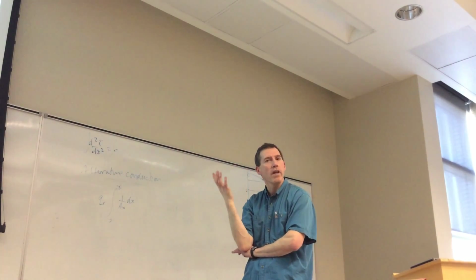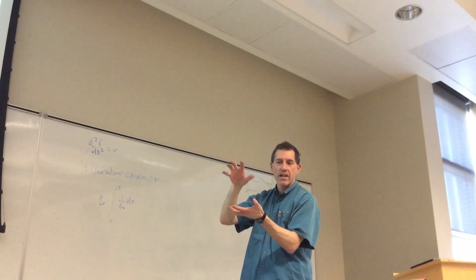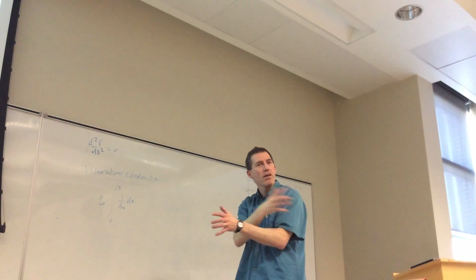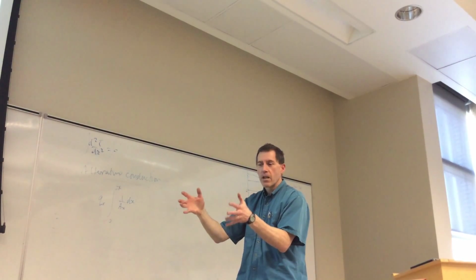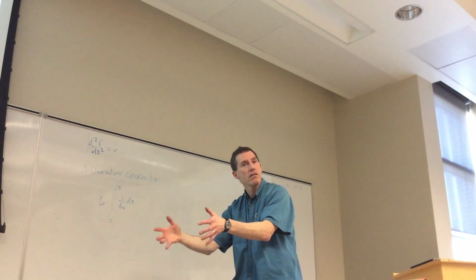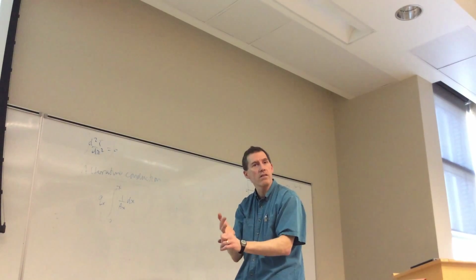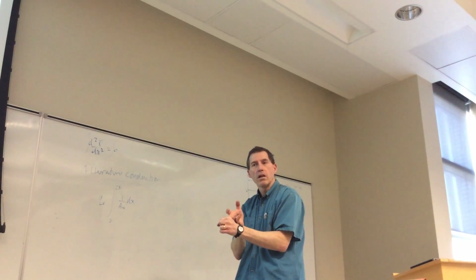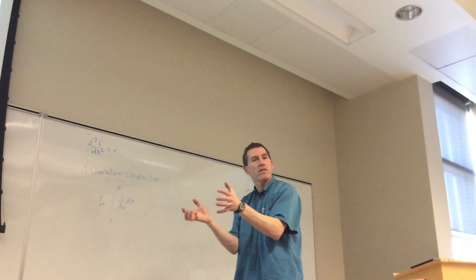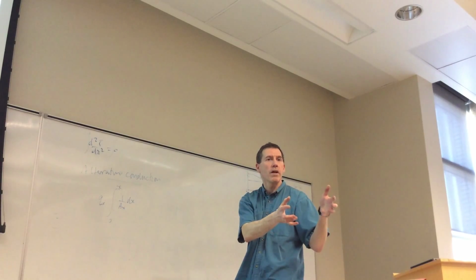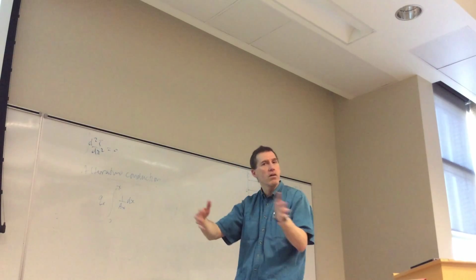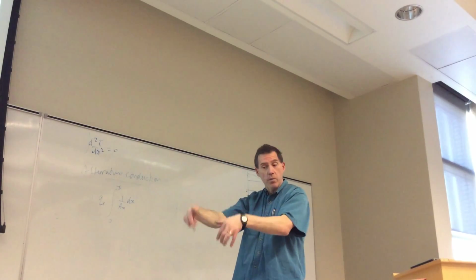So that's the thing. Why do I do that? Because I want to know whether the person understands the final equation. Take the fins as an example. I can't give another example without saying too much. The question is, does the person understand what the fin is? What are all the assumptions involved in the fin equation? It's constant h, constant cross-sectional area, constant k, all those things. If you change one of those things, you have to go back to the original equation and ask what the piece is that's different now, and how do I do the right integration or differentiation to get what I need for this problem?